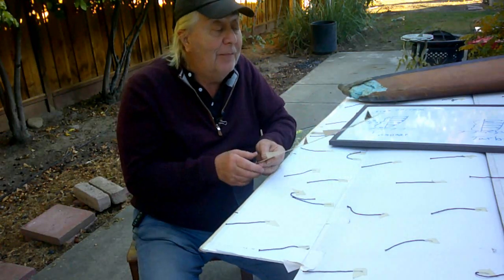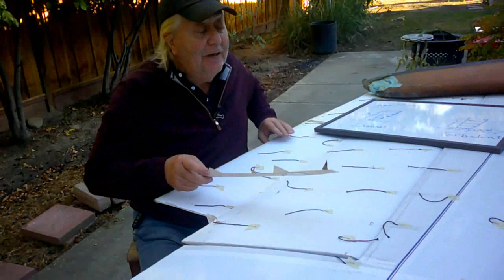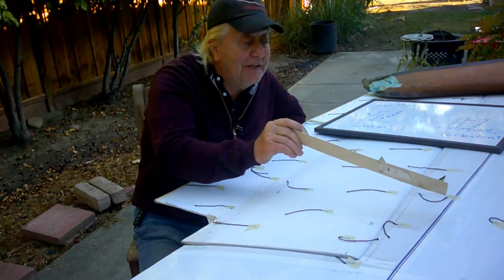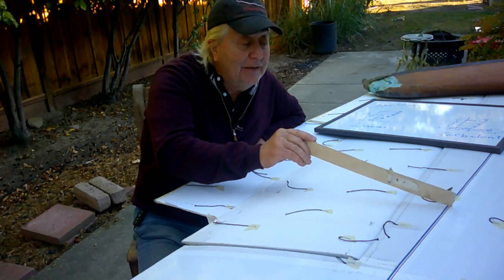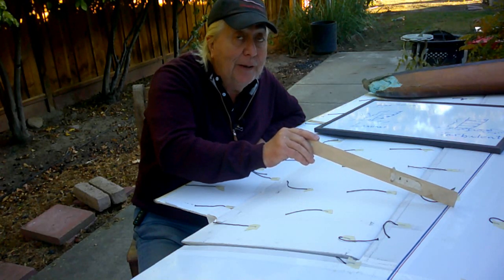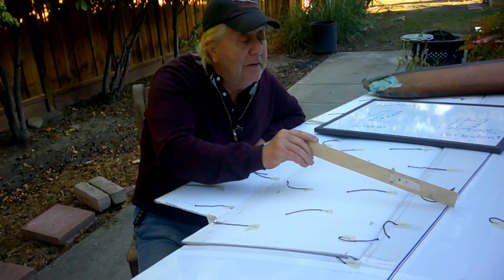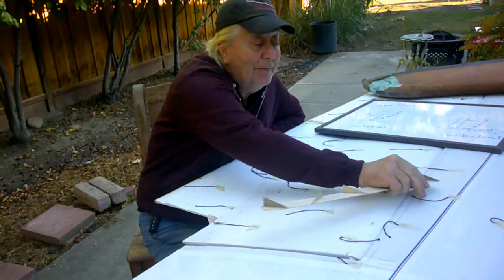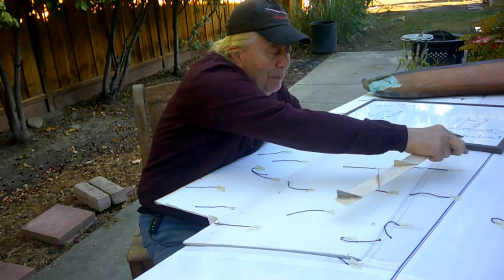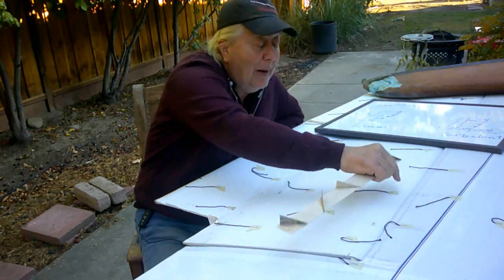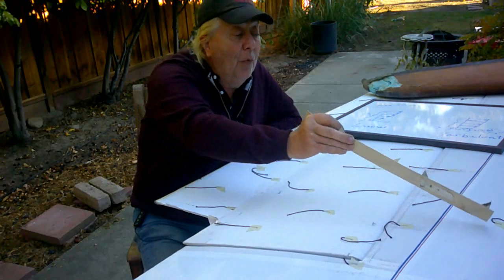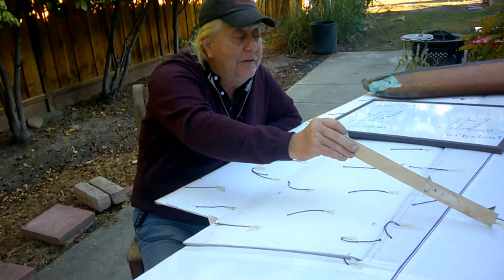And then there's another problem. Nominally, it looks like the optimum location for these vortex generators is not here at the peak of the airfoil, which happens to be where the spar is, not back here behind the spar, where these would be really easy to mount because I could take the fabric off, put a tray in here, with little pop-up vortex generators, but more up here on the leading edge.